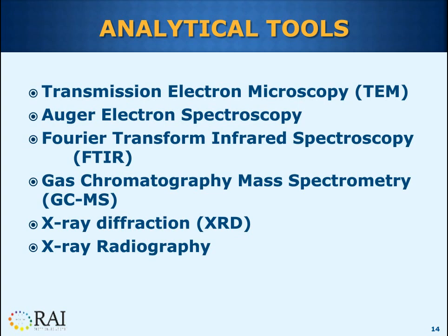Note in the last two slides that there are many different techniques available to a forensic engineer. The choice depends on the type of information needed and the characteristics of a particular sample. It is very important to stress that most times I have to use 2 or 3 techniques that are complementary to best reach unbiased, accurate conclusions. For example, if I'm considering analyzing a plastic material, FTIR analysis, which is basically infrared analysis, might tell me the sample is either nylon 6 or nylon 6,6, which are 2 different types of nylon.